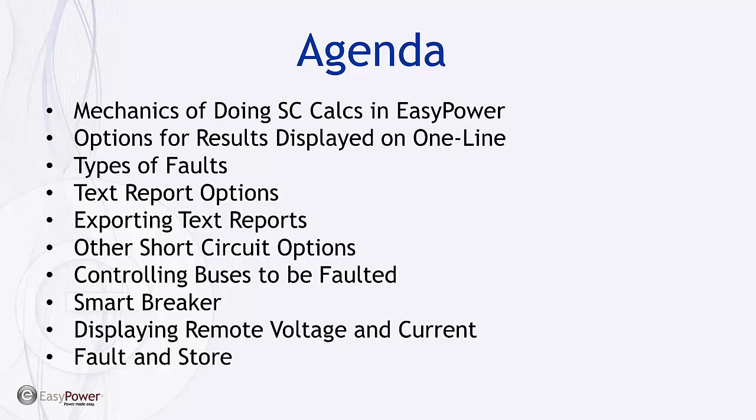I'll look at other options within the program for controlling how the short circuit calculations are done. And we'll look in some detail about how to control the buses that are faulted when you run the short circuit calculations. It's not necessary to fault every bus in EasyPower when you run a short circuit calculation. We give you a great deal of control over how that happens.